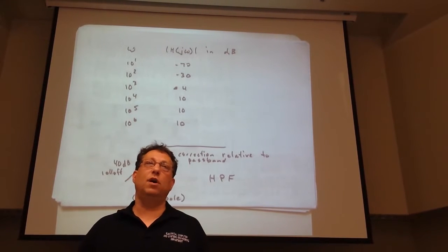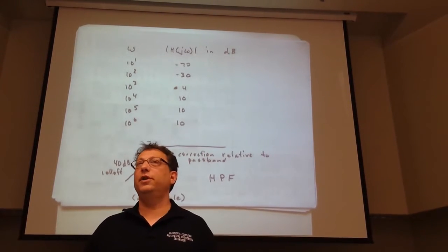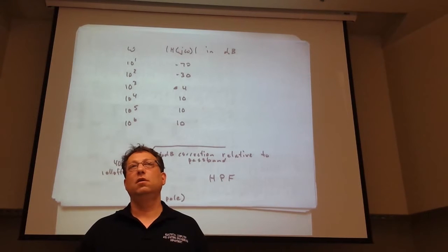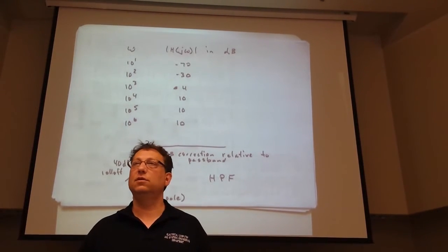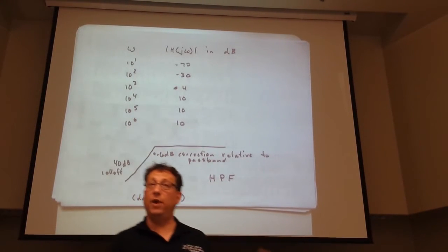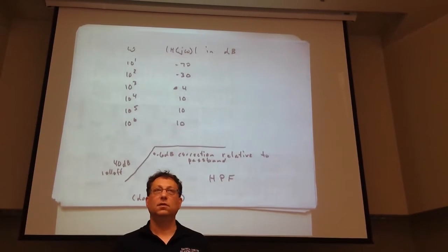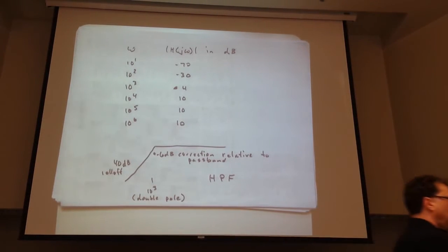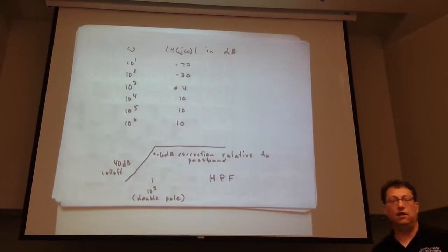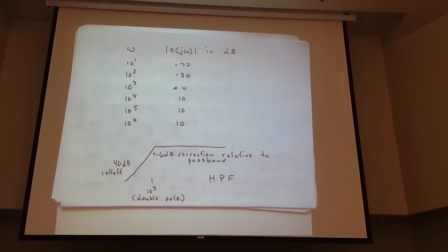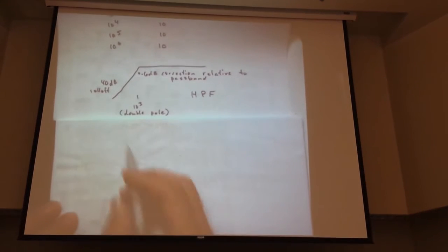If we're talking about real poles, can we build this circuit with first order filters, first order stages? Yeah. Can we build it with a second order stage? Sure. So if you have 2 real poles, you can build this with an RLC second order circuit, or you can build it with cascaded first order stages. What does our transfer function look like? This is a high pass filter.